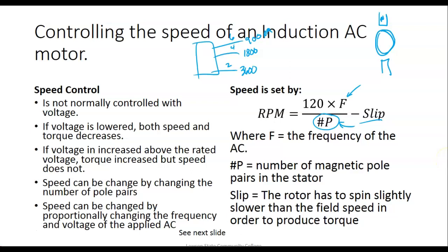So if we've got a rotor, it runs off induction. These are induction motors. So what happens is if these guys get in sync with each other, then there's no difference to create the relative motion between the two. So that means the rotor will always have slip.